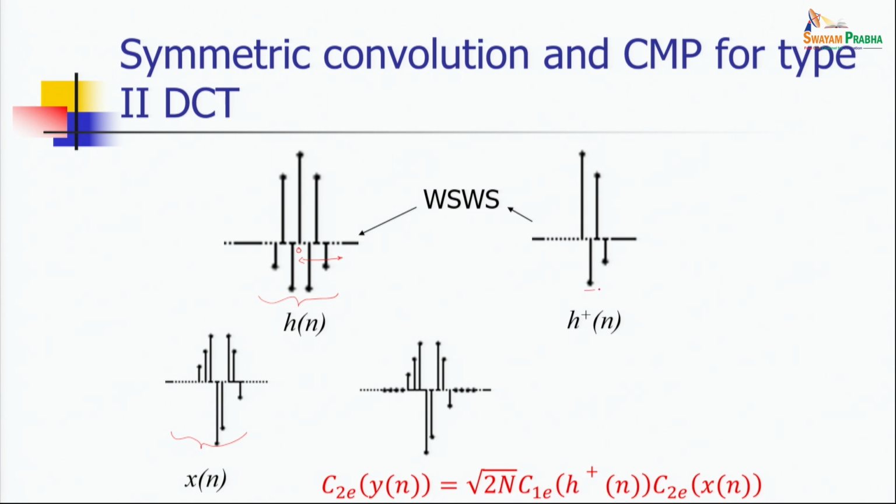Here it is the positive side of the filter response, because on the negative side you can apply the symmetric extension. Here it is whole symmetry extension. That means at its two ends, this end and this end, you are applying whole symmetric extension. About this point, the response would be this, and then you get this. Similarly, about this point, once again, it will be this.